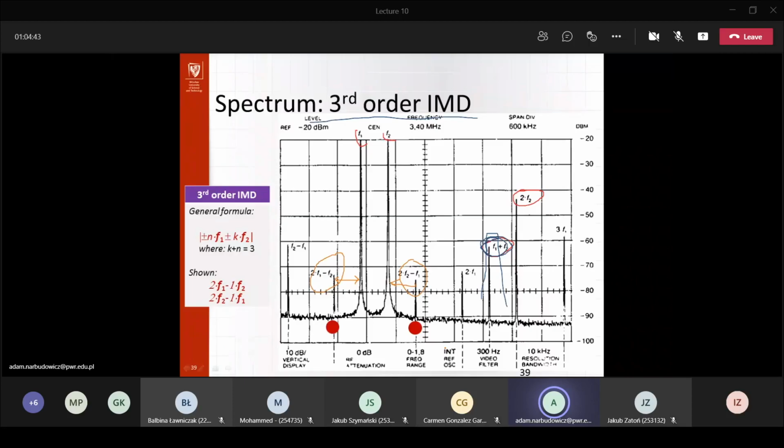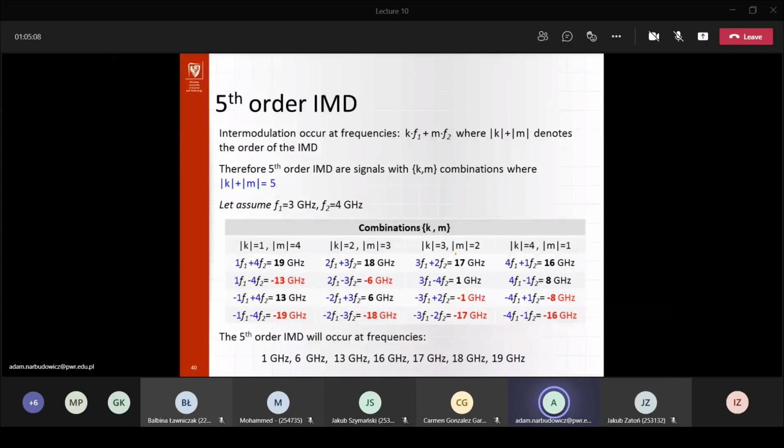It's very easy to miss something, because your test might not involve enough power to drive the nonlinear range, or simply because the tests are complicated and nonlinear. Okay, so basically then we have fifth order intermodulation distortion, or intermodulation products.